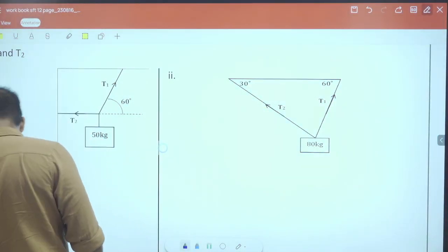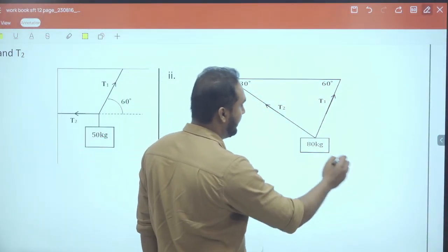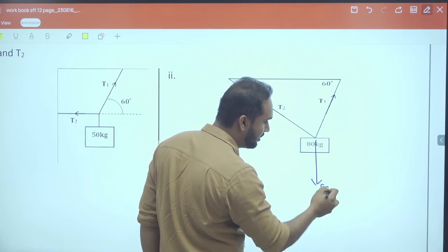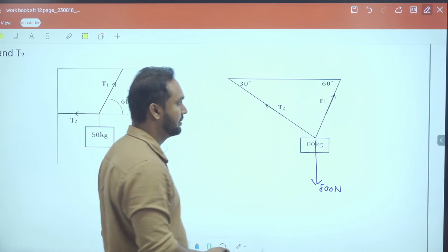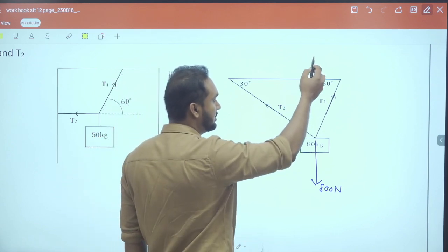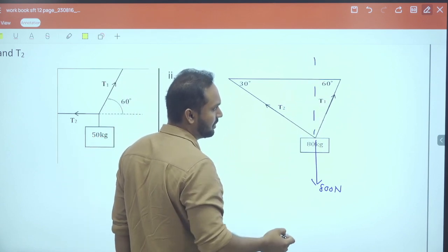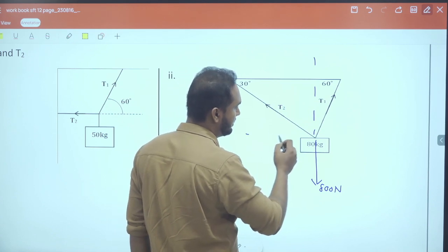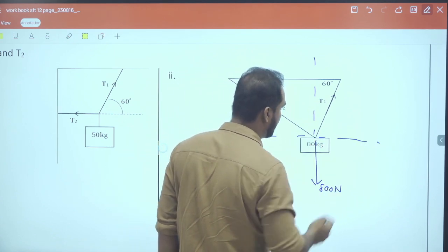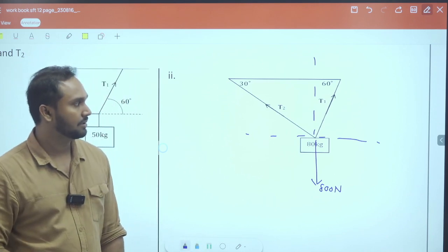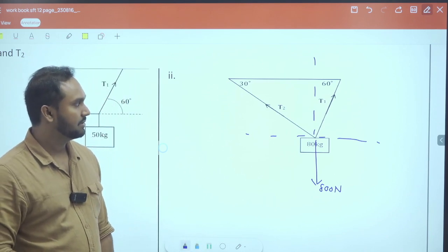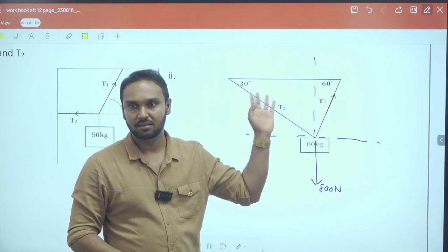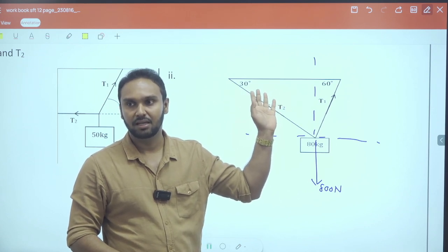Okay. Right. So 80 kilograms means there's 800 newtons acting downward, right? And you take the two axes, the vertical axis and the horizontal axis. These are the two axes you have to be concerned about, because if the forces are acting at angles, you can't take them into the calculations directly when considering the equilibrium.